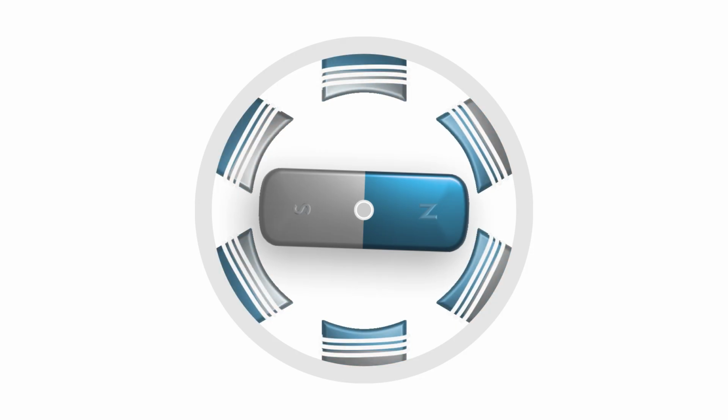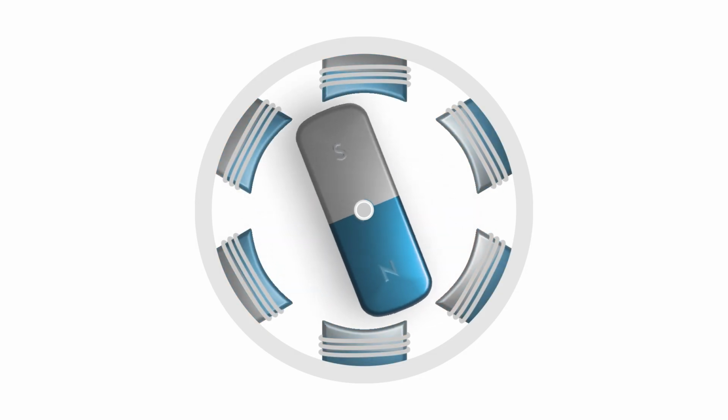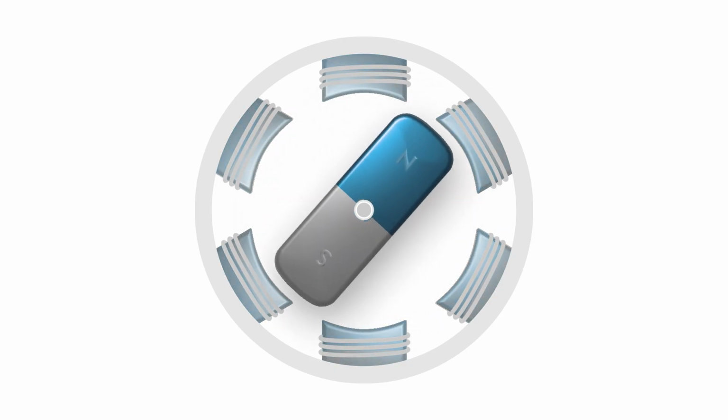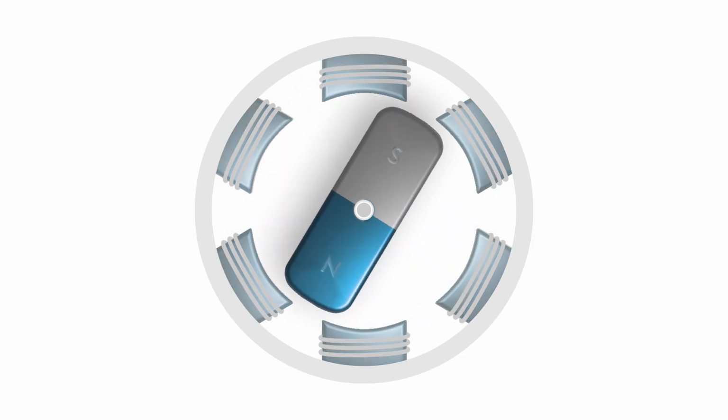This is the same principle as in the coil winding. Deliberately reversing the polarity of the stator magnets with a continual change in the direction of the coil current changes the direction of the magnetic fields and generates movement. The attraction between permanent poles here in the rotor and the changing poles in our model in the stator leads to continual rotation. This principle can be reversed.